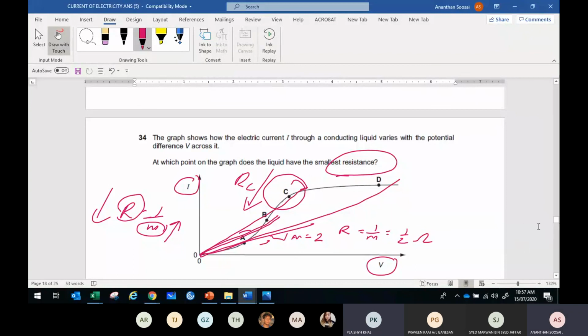In real life, let's say in your house, maybe you have a light bulb. An external light bulb for the car. Maybe the car breaks down and you want to use a light bulb. You have a battery in the car connected to the light bulb. You want to get the maximum brightness for the light bulb. You know the resistance of the light bulb. Let's say the resistance of the light bulb is 2 ohm. Then the battery internal resistance must be 2 ohm. Then you will get the maximum brightness.